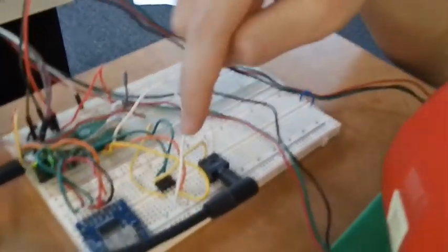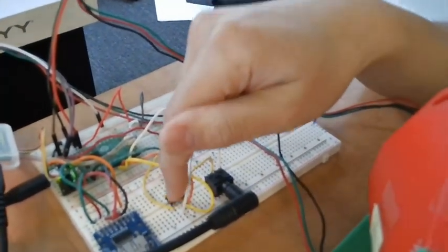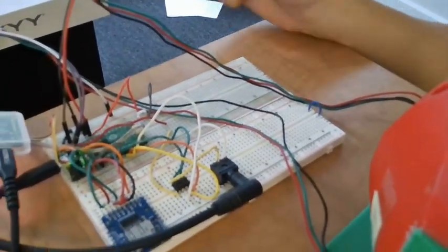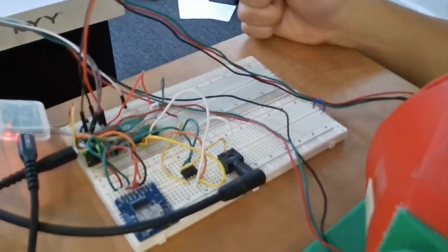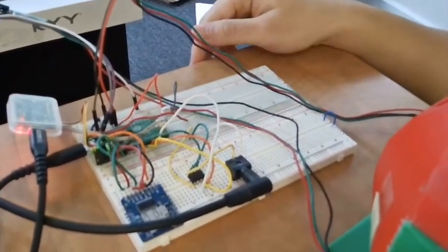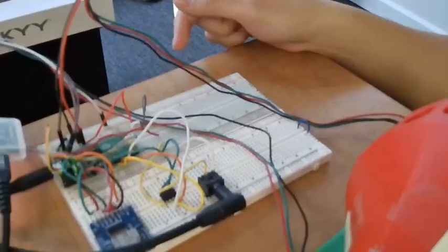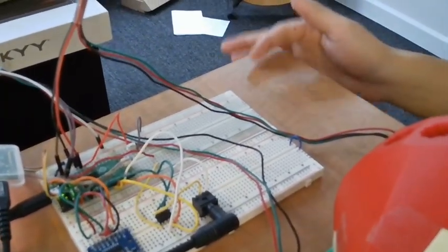And then there's also a DAC. It's a 16-bit DAC. 4 of those most significant bits are for control. So we effectively have 12 bits for audio payload. And since all the audio files we synthesized were 16 bits, we had to do some processing to convert between the two formats.